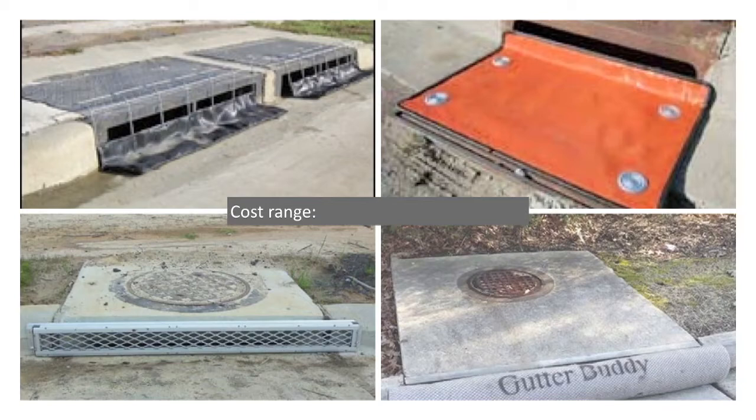But you have to have overflow capability. If it suctions up next to the curb, it's going to cause a problem. In some cities, during the rainy season, they make contractors pull them out if they don't have the overflow capability, because they can't have flooding. No matter what, you cannot have flooding.